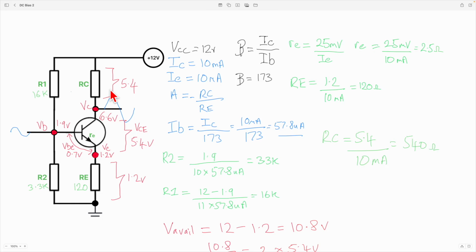And as I said, although I'm writing 540 in there, for mine I didn't even go to the bother of that. You can probably get away with just halving the power supply and biasing this for 6 volts, because it's pretty much that anyway. And that is the DC biasing done.